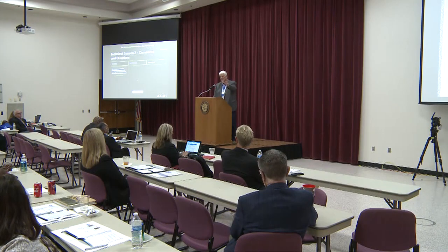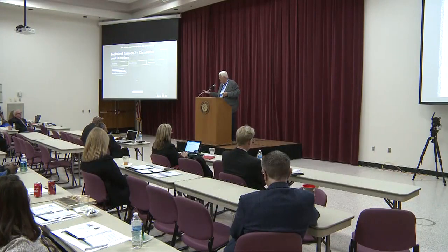TSR, yes, we've got a special committee right now looking at TSR, T283. The test itself is so wide and influenced by so many environmental issues. Yes, we're trying to take a look at TSR and stripping. As I noted back on the rutting test, the Hamburg can help address stripping issues. We're looking at other alternatives for TSR, maybe go to the Hamburg and identify stripping and take a look at it that way. So yes, but with some caveats.